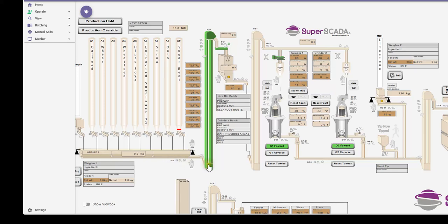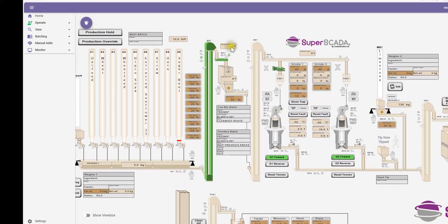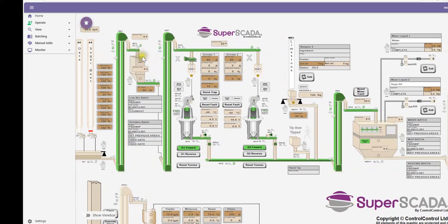finished. Now cleaning up this elevator here, and you can see there's a timer here for the clean out time still to go, for it to go into this grinder buffer bin, or actually it's a live bin. And now what it's doing now is it's starting up the discharge from there up to these grinder buffer bins here, and it started the grinders already. They took a little while to start, and it's now going to the mixer over here.